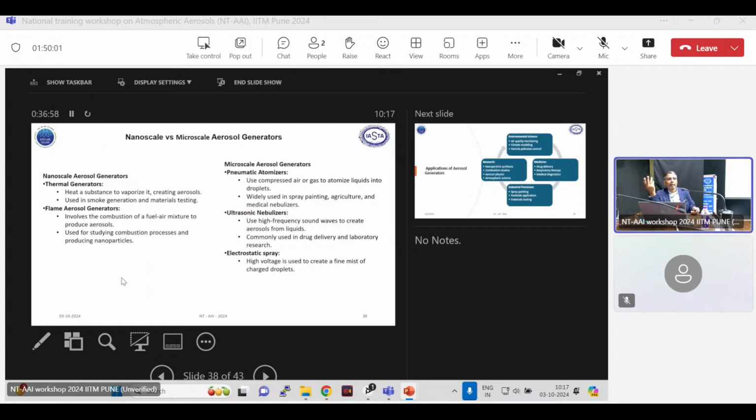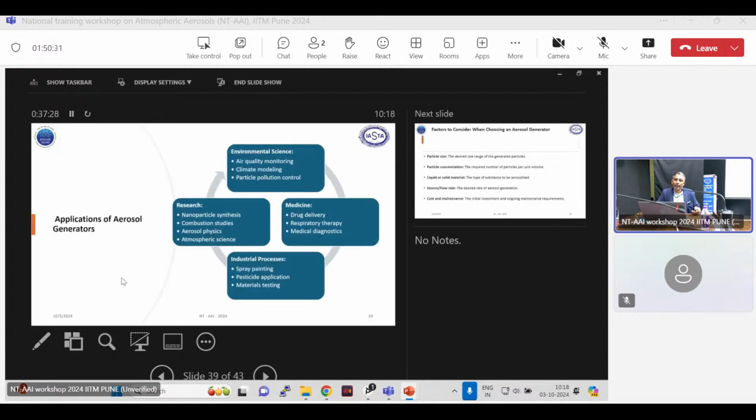Any sprayer, nebulizer or atomizer will produce micron or larger particles. And powder dispersion or fluidized bed aerosol generators have larger diameter aerosol. So based on that, you may now understand which principle they use. Aerosol size depends on the fundamental principle of how they are generated.